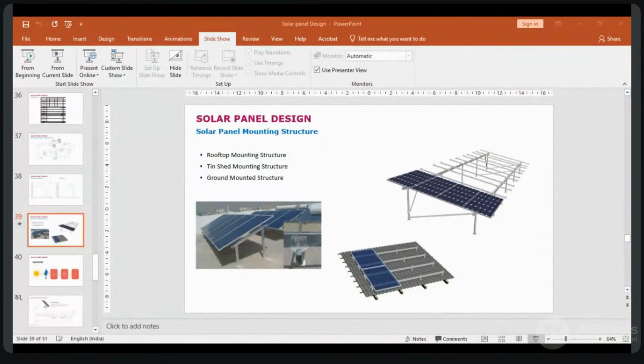And the last thing of this session will be earthing. We have two types of earthing generally for designing a solar panel: one is AC earthing, another one is DC earthing. What is earthing? From the sun to the solar panel, we have DC power only, so there we will do DC earthing. In earthing we need to consider indoor and outdoor. Outdoor is the sun and panel. Indoor is generally the MPPT module, grid inverter, and load.